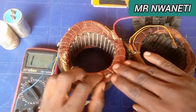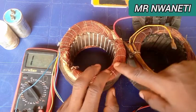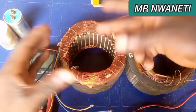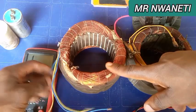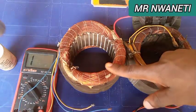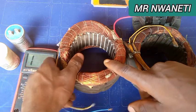And maybe you depend on the value of the capacitor you put on it. So this coil is like two times what the winder did, two times the coil. Despite that they use 0.7 mm here and I use 0.6 here, I will do some fraction. So the turns are huge, the multiplication is huge. From the exciter, when you put 24 uF, we have a drastically high voltage. So I put about, I think, a 12 uF capacitor. So it gives me high voltage.